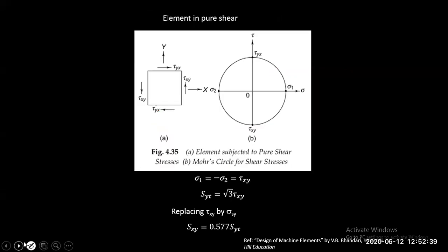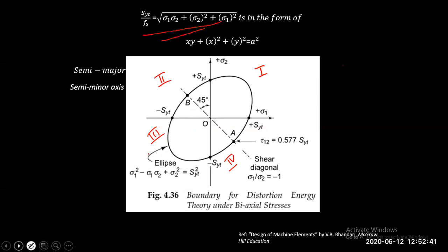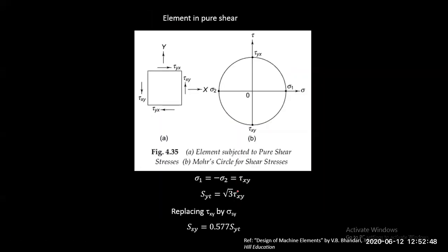So this is just the pure shear. If you consider this von Mises stress equation, if you consider this circle here and complete that circle, you will get a state of pure shear, and this is the maximum stress. So this value is nothing but tau, the shear stress. Shear yield is equal to this. This is the yield stress. So that's how it's related. Almost 57% of yield stress is regarded as the shear stress value.